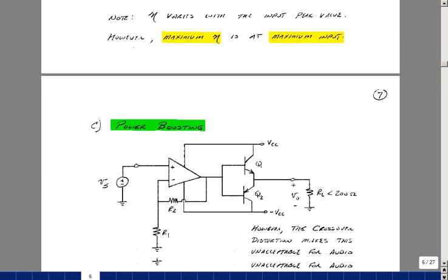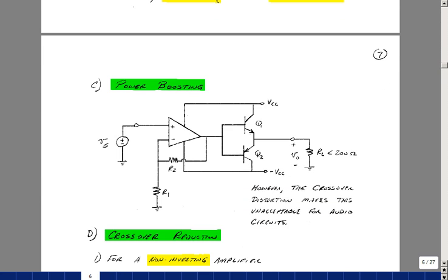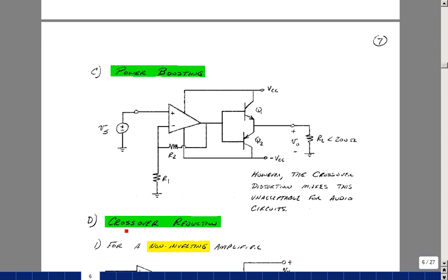So we could take this complementary pair set of transistors where we've got an NPN and a PNP, just tack that on the back of, say, a non-inverting amplifier. What we're getting now is essentially a current boosting. See, we have up to 25 milliamps here, and that's going to become, if it's positive, the base current of Q1, and then I can get beta DC, or even the beta AC, times that base current.